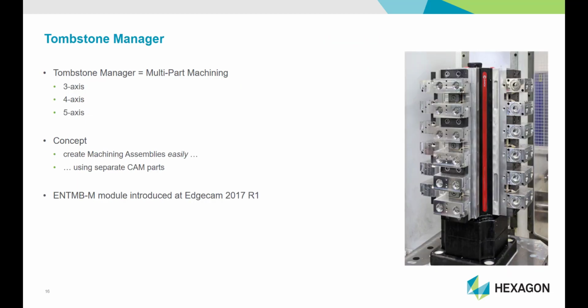The next area we'd like to explain is Tombstone Manager. This module allows the assembly of unique completed CAM parts into a single CAM file. Think of it as an assembly, for purposes of quickly creating an efficient production run. Tombstone Manager is developed to simplify the complex CAM process of setups with multiple parts.